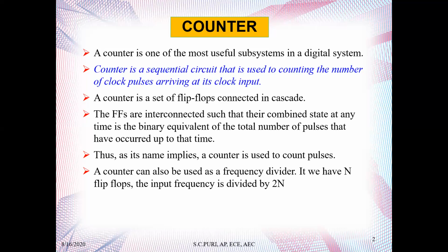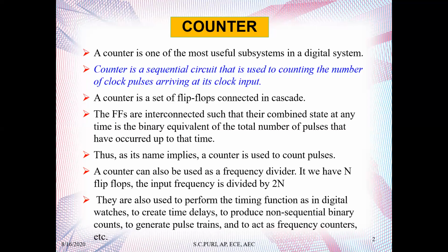A counter can also be used as a frequency divider. If we have n flip-flops, the input frequency is divided by 2^n. They are also used to perform timing functions, as in digital watches, to create time delays, to produce non-sequential binary counts, to generate pulse trains, and to act as a frequency counter, etc.